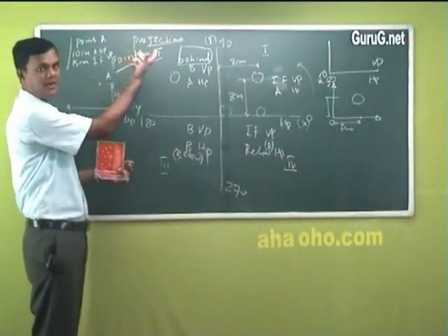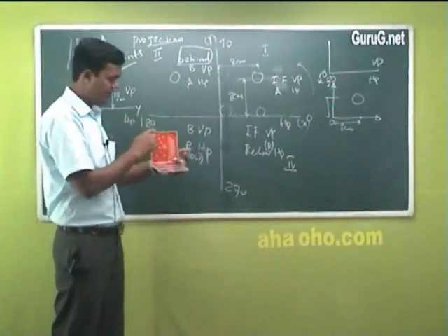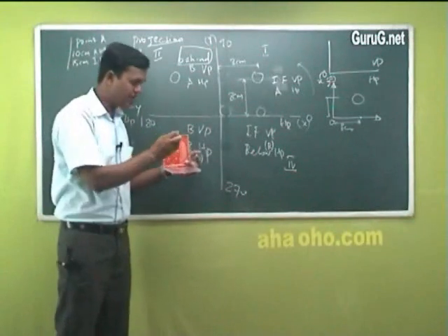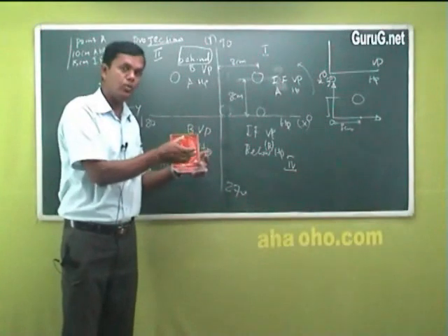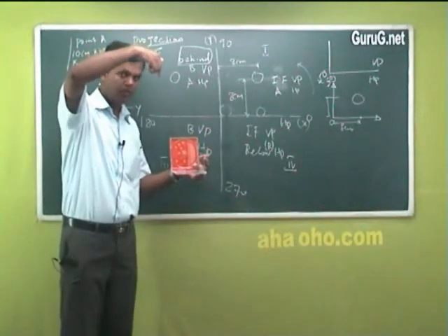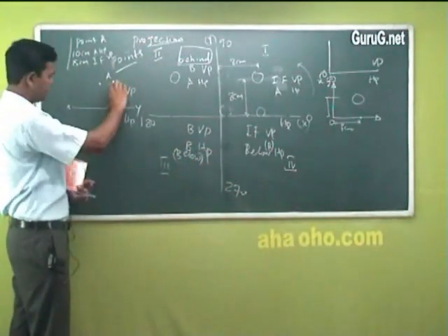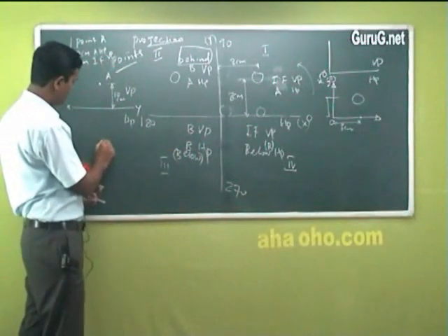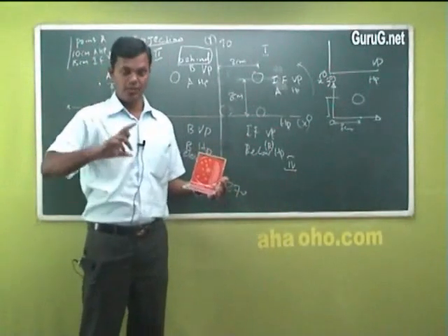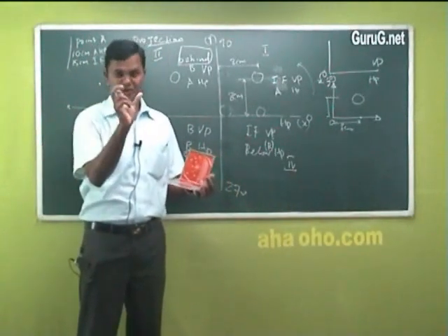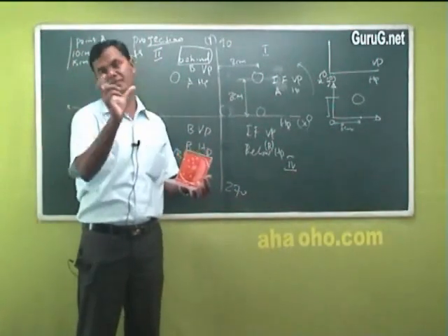15 centimeter in front of VP is the question. In front of VP, how will you show it? Actually VP is here. In front, it is 15 centimeter. Somewhere here it is. So this distance can be viewed only through the top view. Fine. So you view it here. 15 centimeter is a bit more, this is small, 10 centimeter. 15 will be like this here. See, kindly remember, the point is only one point. We don't have 2 points here. The point is only one, but it has a distance of 10 centimeter above HP and 15 centimeter in front of VP.